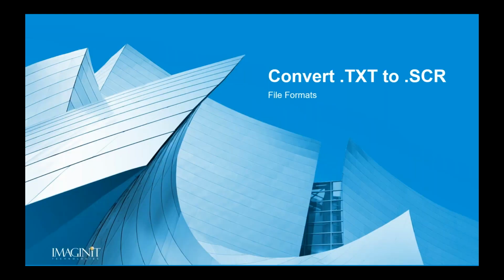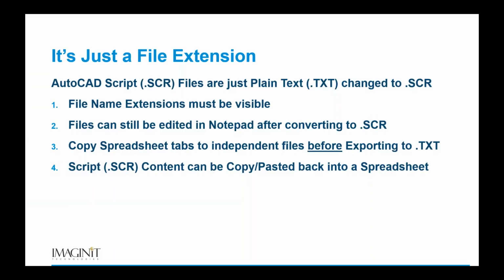So converting TXT to SCR files, it's really just clicking on it. The only issue that you're ever going to have is if you've got your Windows set up to hide file extensions, then you're not going to be able to get to that .txt extension to change. Beyond that, it is really just clicking on it, deleting the .txt and replacing it with .scr. Once you do that, it's going to change the icon.